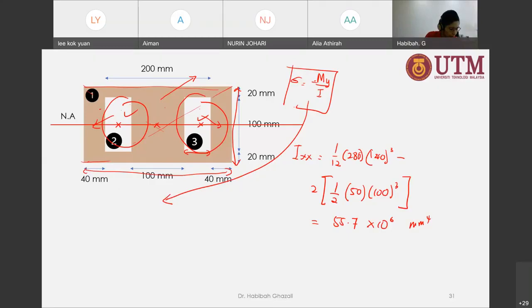For the brass, we take this part, because that's where the maximum for the brass is going to be. That's where it's bonded together. So for steel, you need to transform it back. It's going to be times 2 of what you have calculated, and that would be 20.1 megapascal. And for the brass, it's going to be 7.18 megapascal.